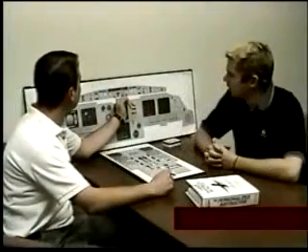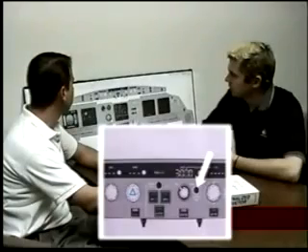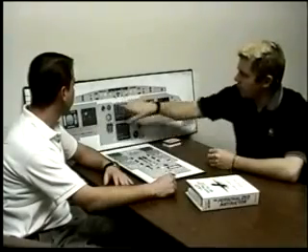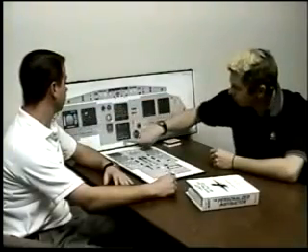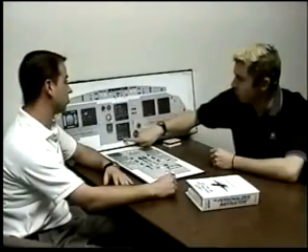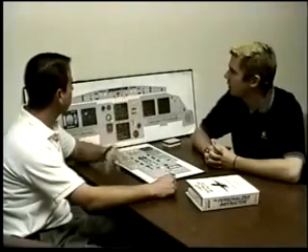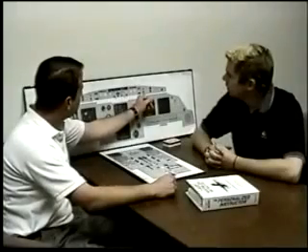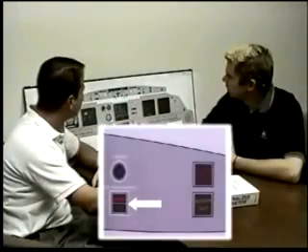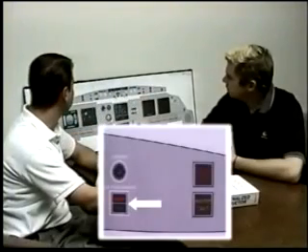On the FCU, there's a push button for metric altitude. What would happen if you select that? By selecting that, I would not change the altitude over here to meters. It would stay feet. But down here, just above the clock, would give me a metric altitude in meters. What about the altitude selected in the FCU? Would that change to meters? That's still feet. On either side, there's a side stick priority. There's an arrow. On the first officer's side, there's an FO. On the captain's side, there's a captain.